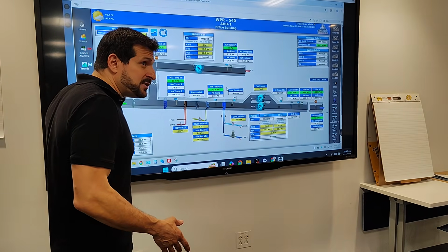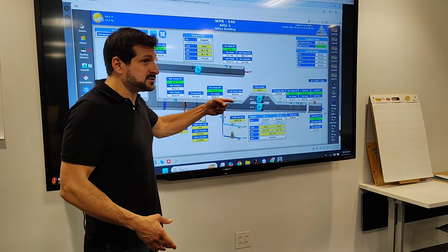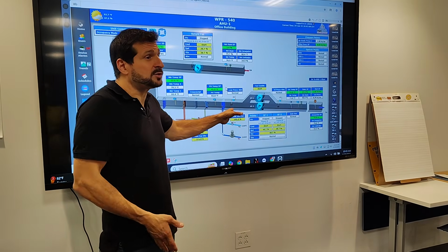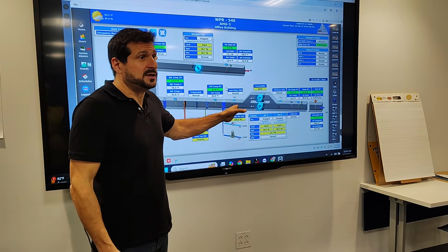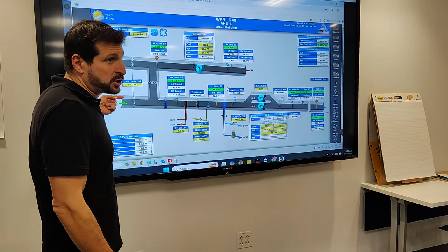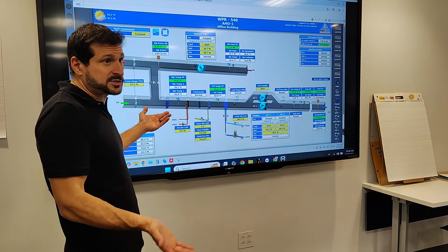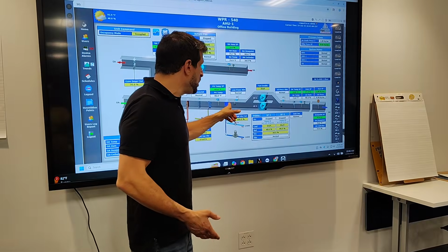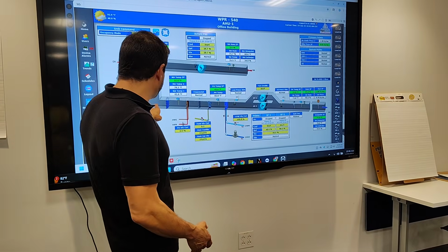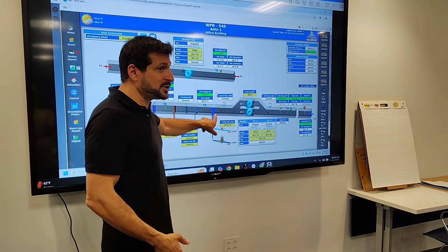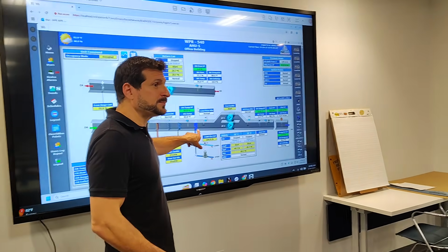Even if you were bringing in 80 degrees from the outside, even if you're bringing 85 degrees, this unit's probably designed in New York to be somewhere around 90 degrees at your temperature. Now, that's not at 100% outside air. That would be at a mixed outside air, 40 to 50%, depending on how the building was designed. But if I have a mixed air plenum of 82 degrees, I should have no problem getting to 55 over here.